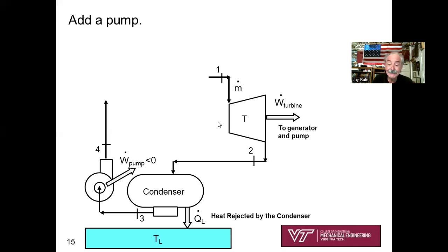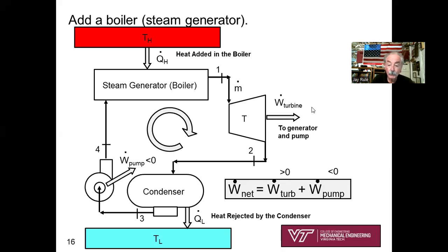Well, we've got to complete the cycle. So we've got a system operating in a cycle. We do that by adding a steam generator. It's a heat exchanger again, and you've got some experience with a heat exchanger. You're adding heat to compressed liquid water and turning it into superheated steam. And that's what enables you to complete this cycle. So, getting you ready for chapter 5, notice I've drawn my block arrow going clockwise. So the sketches kind of fit together, and it should make sense to you.